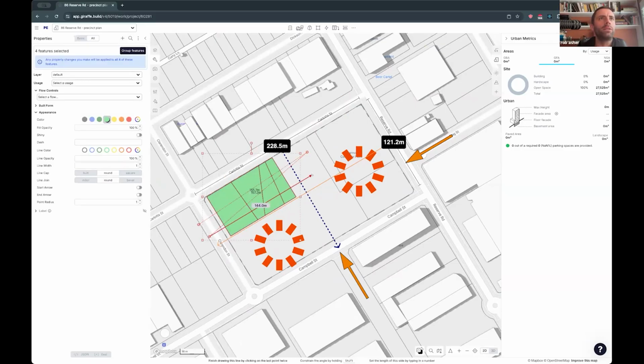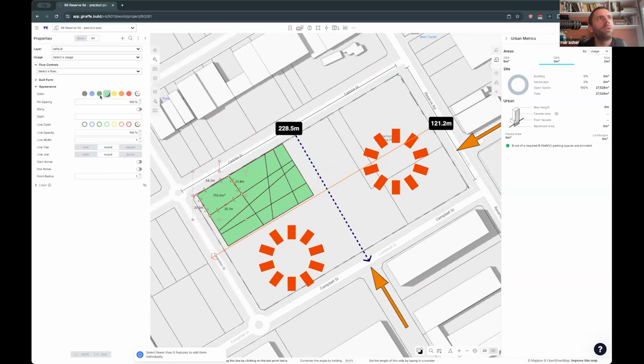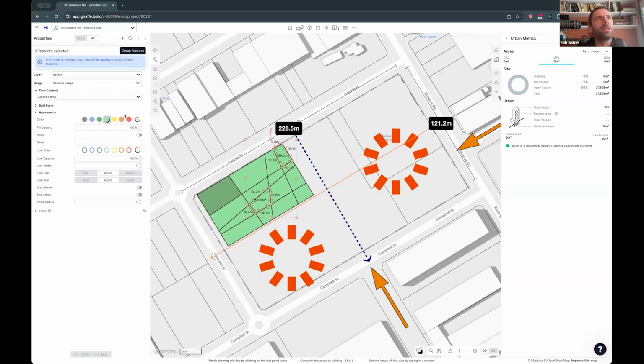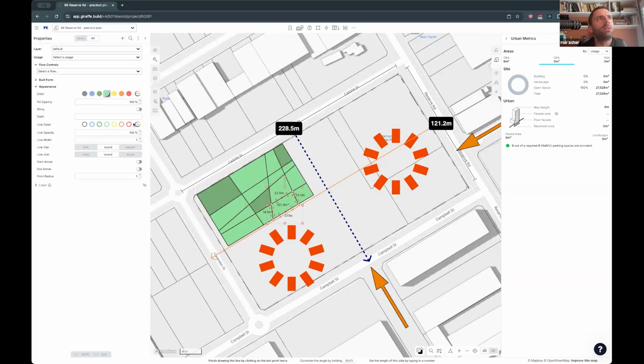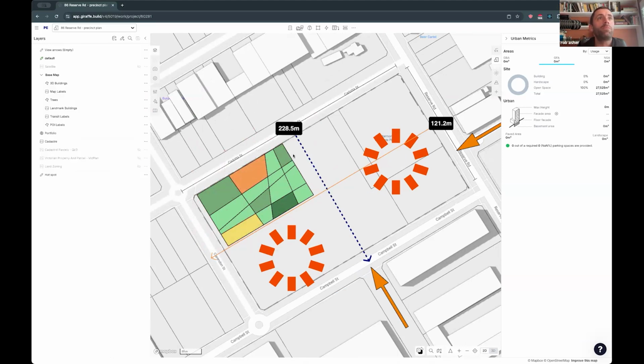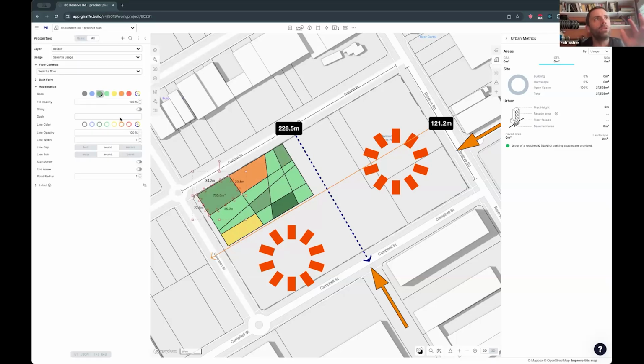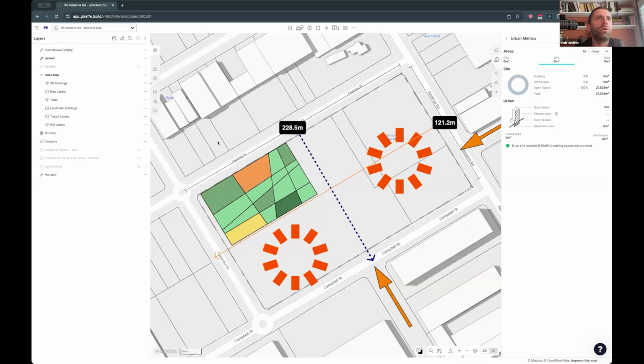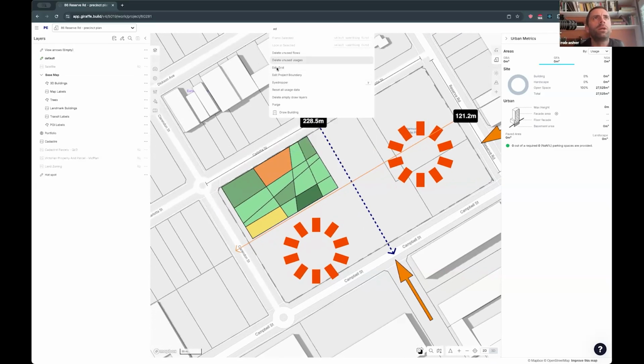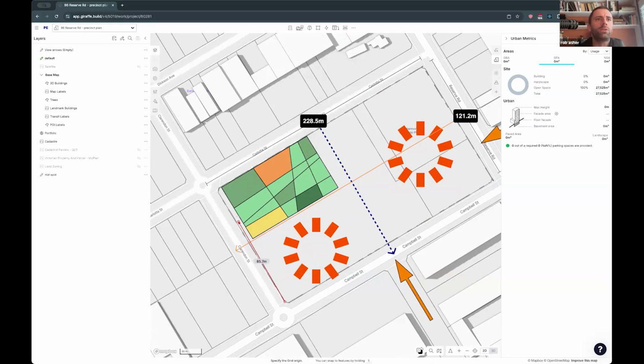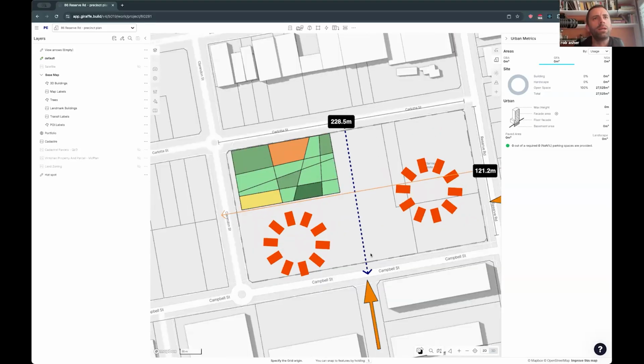I'm using the X key here to slice this thing up, and I'll show you slice in more detail. But you can see here I can make a cool little park very, very quickly with some fun places to hang out just by using those properties and working with them quickly. I'm going to edit the grid. So I hit the space bar to get into the command, and I'm just going to snap this grid up. I'll do a 2-meter planning grid and snap like that.